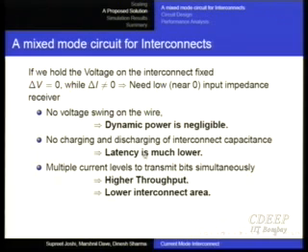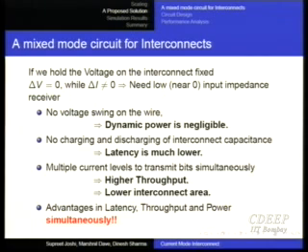Let's try it. There is one little problem. You need an amplifier with 0 input impedance. Okay, so all of this will be a pipe dream if you did not have an amplifier which can provide 0 input impedance. In fact, we would like an amplifier which would have slightly negative impedance, which when put in series with the resistance of the wire will give me 0 impedance at the transmitter. Okay, so the total impedance seen by the transmitter will be 0. Okay, so naturally when we got this idea, I started looking in the literature for a negative or 0 input impedance amplifier.